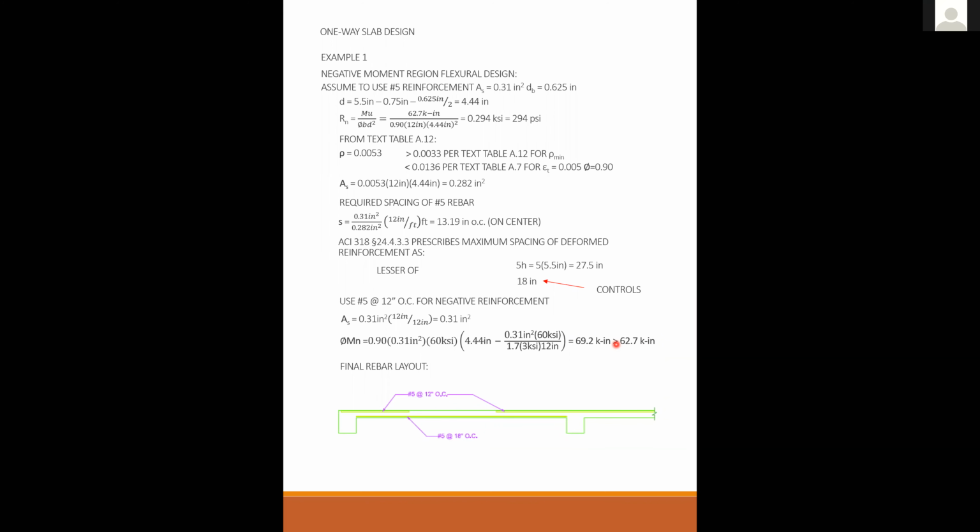So it's under-reinforced, in the sense that you didn't put enough reinforcement in it. But it's not technically wrong if your epsilon T is between 0.4 and 0.5, right? Oh, no, never mind, because we used phi 0.9 already.